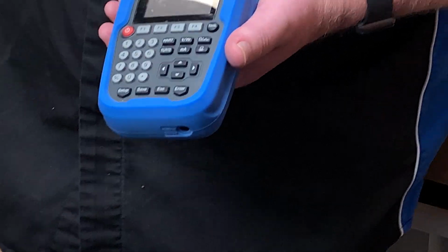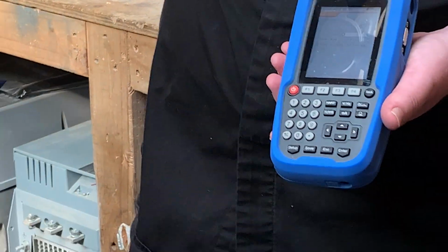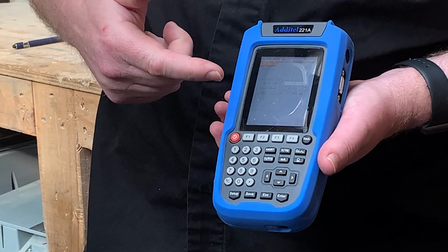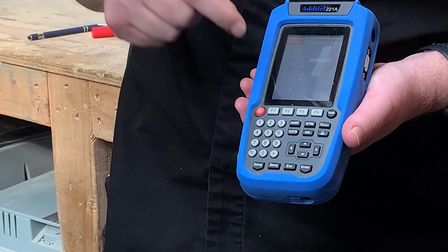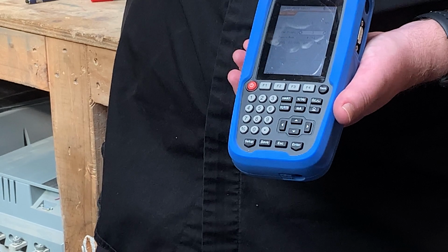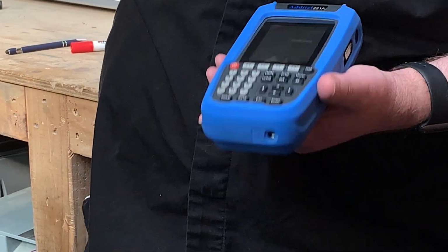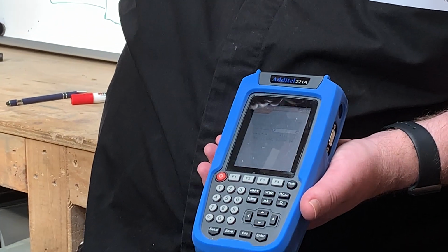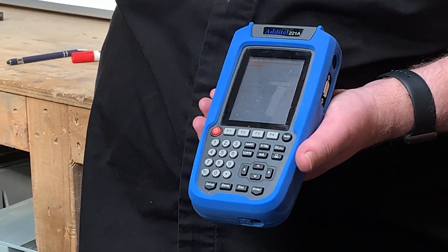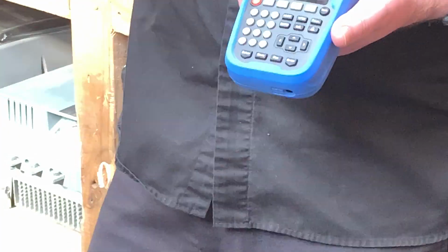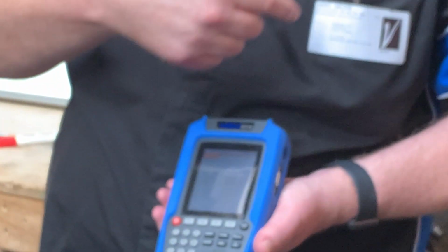Now I've chosen a bad example. I should have chosen a more automatic one that had a transmitter, for example, because this will require manual entry. The person's going to have to look at the screen and go, I'm at 4 milliamps and the display's reading 4.3, and you type that in. I'm at 12 milliamps and it's reading 12.7, and enter that in. If you had an automatic mode, it would measure. So if you were calibrating a transmitter, it would give you the actual output.